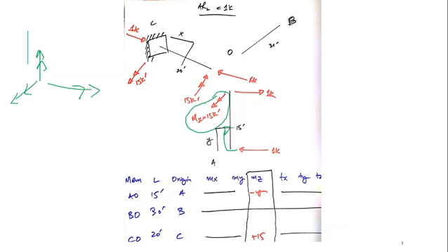This 15 kip foot would be balanced here. It cannot be balanced there because there is no support. So I have balanced joint O with 15 kip foot here. And obviously this rightward force would be balanced here with 1 kip leftwards. This joint is now balanced.